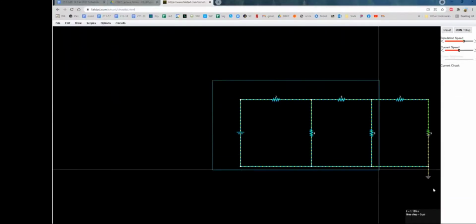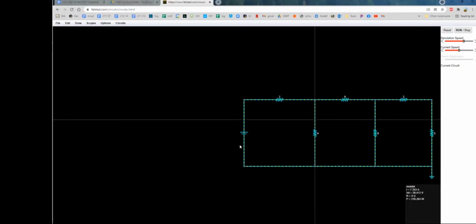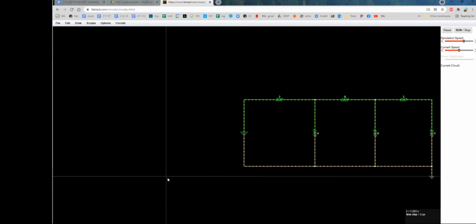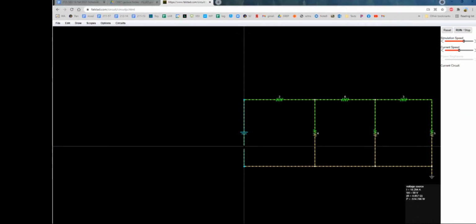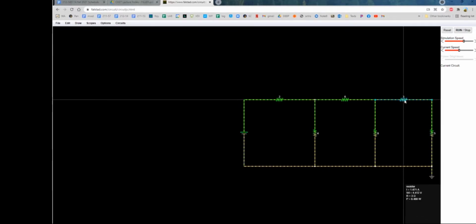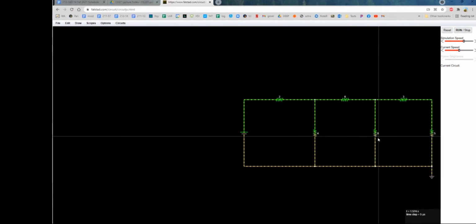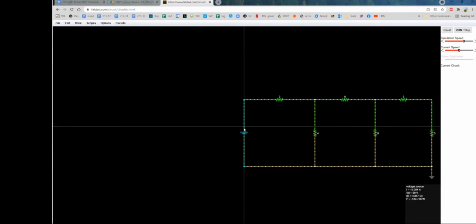All right, so once again, I'm going to bring my circuit, I guess right there's fine. And then Microsoft Shift S. Oh, before I do that, hover your mouse over your battery. So let me double check. My current is 10.294. That's circuit current, the current coming out of my battery. And this is going to be interesting. It's saying my circuit resistance is 4.857. 4.857 must be the equivalent resistance. So if I take 3 and 5 is 8 and then collapse them. All right. So anyway, let's all just agree on these numbers. We're going to do that hard work coming up.